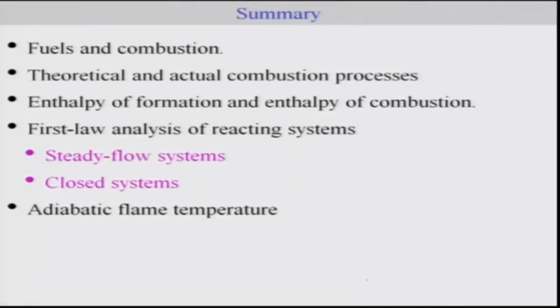We have gone through the definition of fuel and combustion, theoretical and actual combustion processes, enthalpy of formation and enthalpy of combustion, as well as the first law analysis of reacting systems, including steady flow systems and closed systems. We also discussed the adiabatic flame temperature, which acts like a theoretical limit for the design of the chambers. In general, we should be aware of the maximum temperature it can yield, and we can control this by use of excess air.